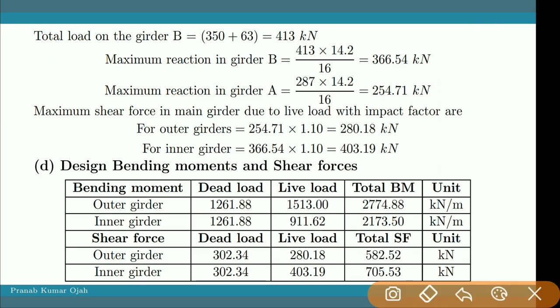So these are the design bending moments and shear forces. I have shown all the bending moments and the shear forces for dead load as well as live load in the form of one table, and then I have calculated the total bending moment as well as the total shear forces. I have gathered all the values into one table, which will help in our next design part of the girder.